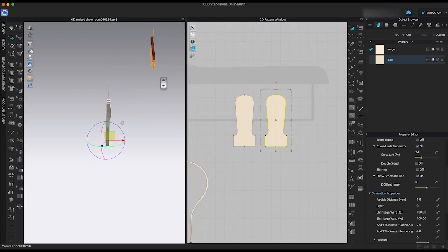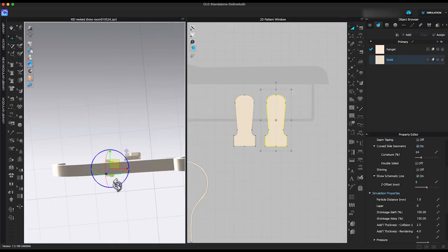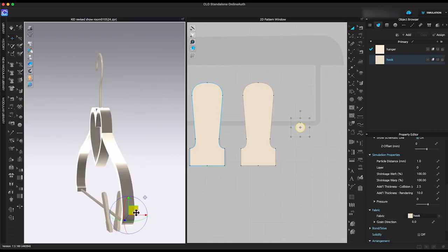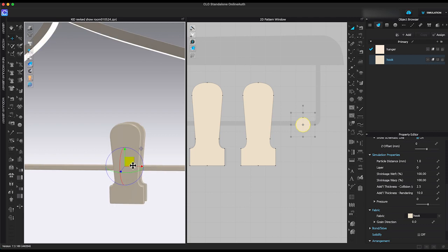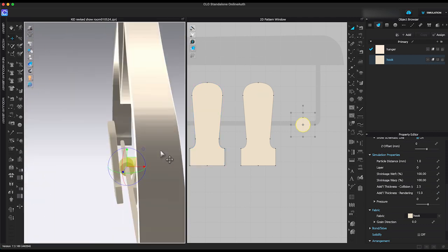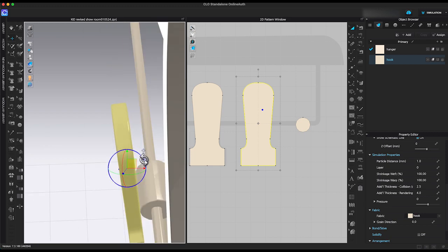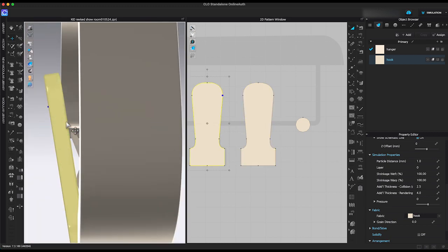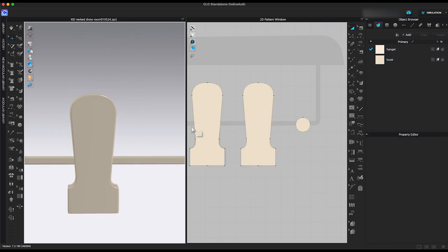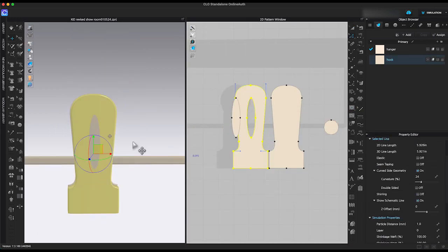Create a duplicate and place it on the back of the hanger bar. Make sure to leave a space between two clips, so you can insert your garment later. Repeat the same process to finish the hanger and export as OBJ.